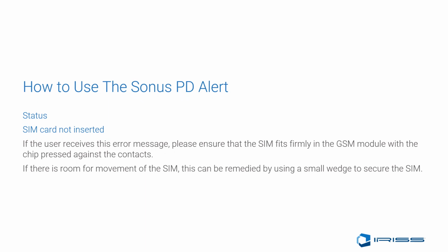SIM card not inserted. If the user receives this error message, please ensure that the SIM fits firmly in the GSM module with the chip pressed against the contacts. If there is room for movement of the SIM, this can be remedied by using a small wedge to secure the SIM card.